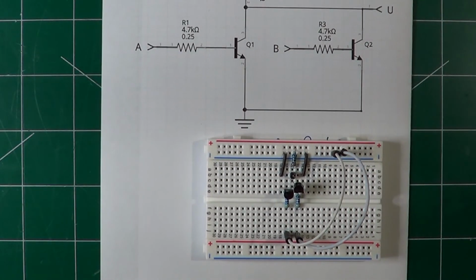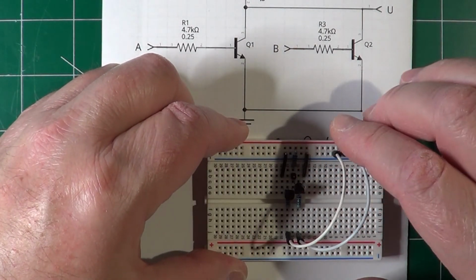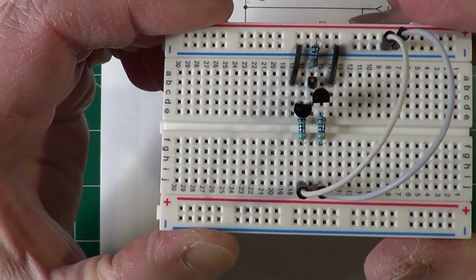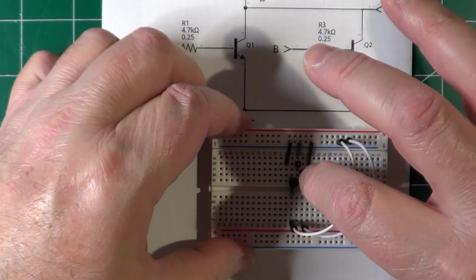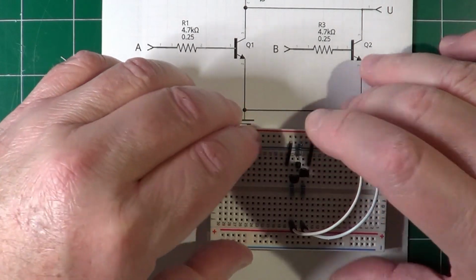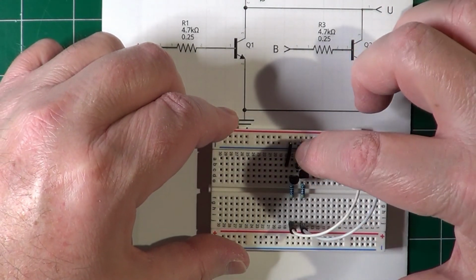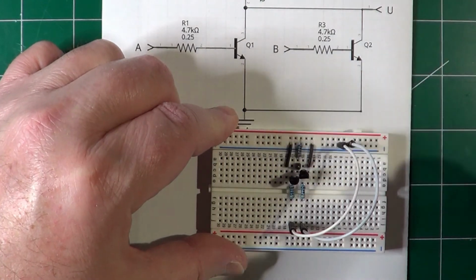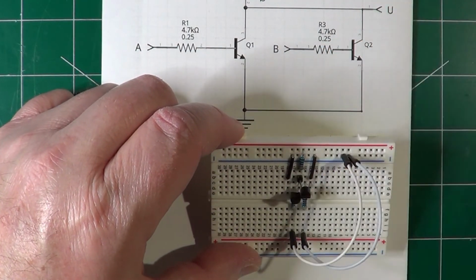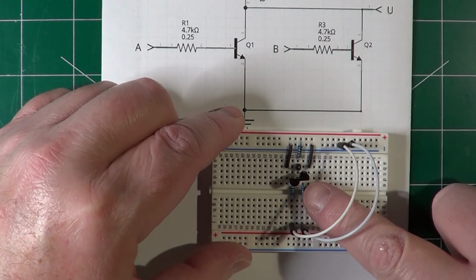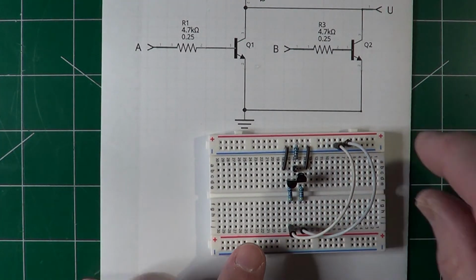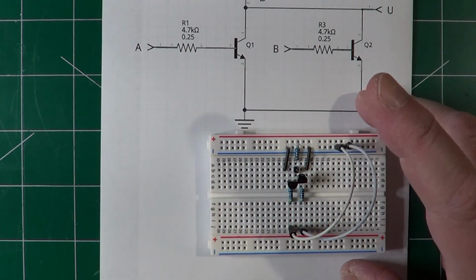Here is the circuit mounted on a breadboard. Here are the 2 transistors. They are mounted against each other so that the 2 collectors can be directly connected to each other. The 2 emitters are both connected to ground. The collectors together go to the positive through this resistor of 330 ohms, and we have also a pin there to be able to read the output with our homemade probe. And last but not least, the 2 resistors on the 2 bases that make the 2 inputs of the gate. The inputs are also connected to ground, the logical 0, through these 2 white wires.